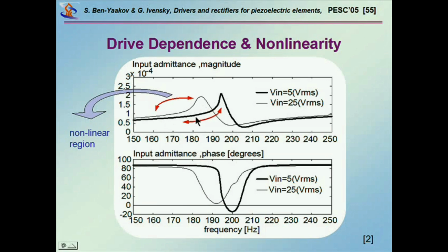The reason is that as you enter into the resonance here, the compliance, the equivalent capacitance, is nonlinear, and since the amplitude of vibration is increasing because you approach the resonance, then you're sort of changing the resonant circuit, and that gives you a different behavior. Of course, with the phase, you see the same shift corresponding to the amplitude.